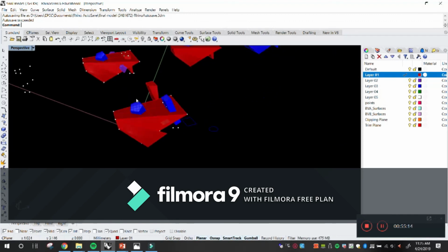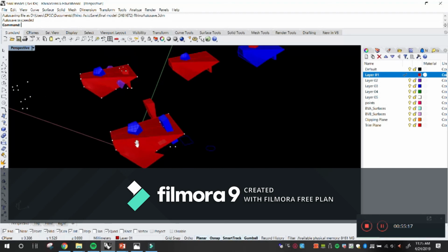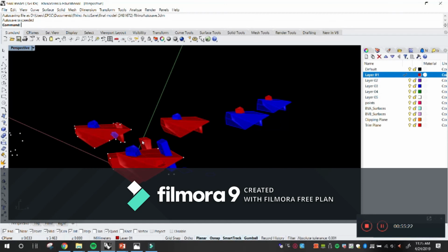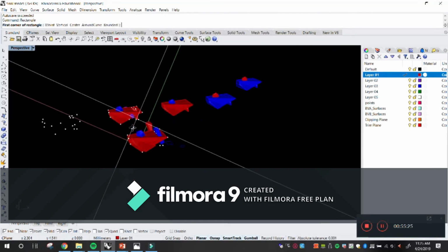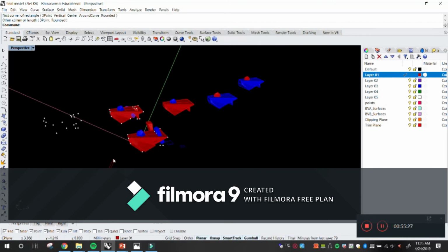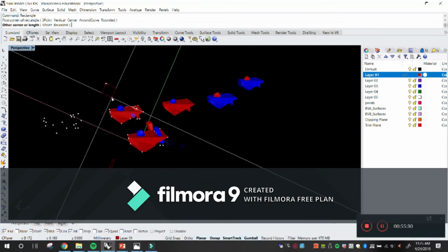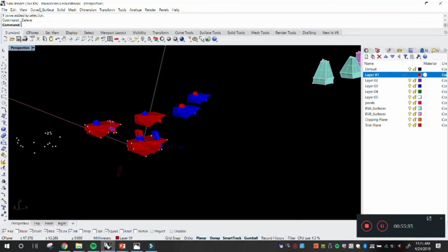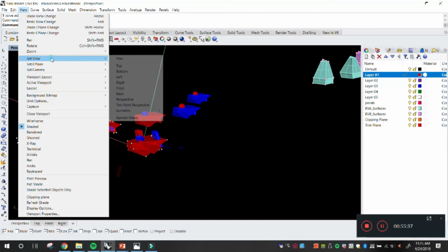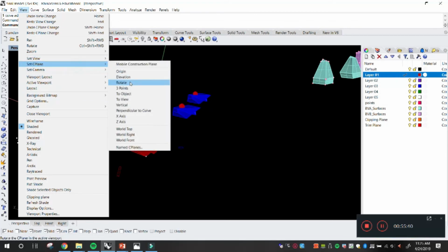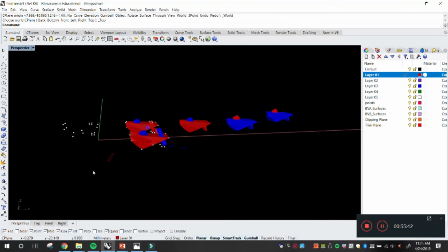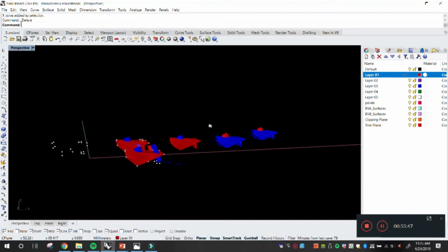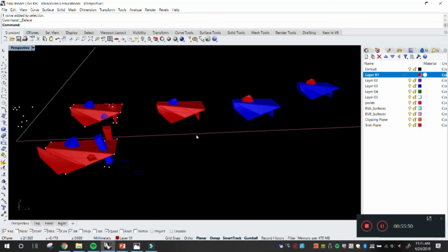All right, guys. Maybe I should open up for questions. Don't forget, if you move your CPlane, I would really recommend that you send it back, because if you try to do something else, it's going to be on that other plane, which is interesting, but maybe not what you're looking for. So, View, Set View, Set CPlane, World Top, and we go back to the normal, regular view. All right, guys. Questions, perhaps something that you see right there on your model?